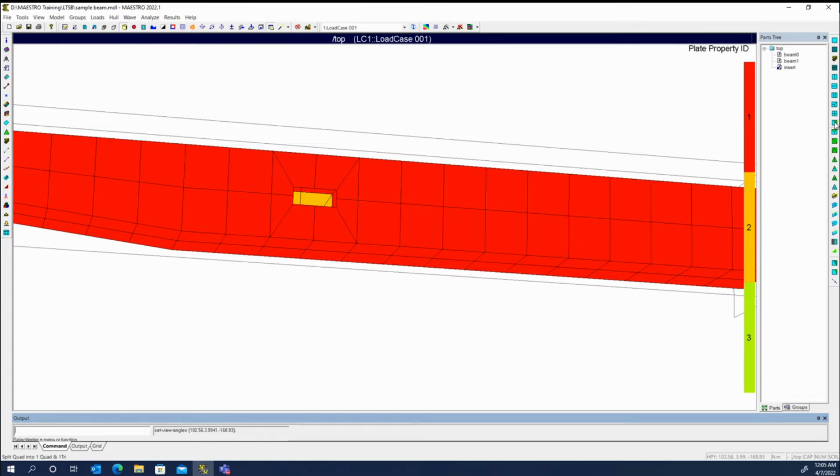So to do that, we'll select the split quad and try, and it wants to split this edge first, so we need to rotate, rotate, rotate. Now that's the edge I want to split, but you can see the triangle is on the wrong side. It's over here. I wanted the triangle over there so that it's coming from that edge. Now there's two things I can do.